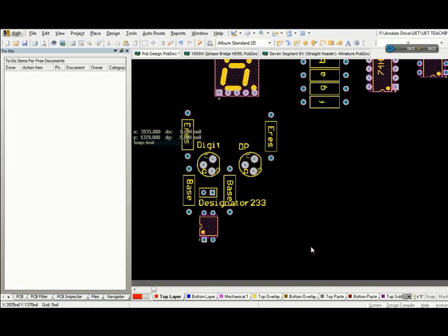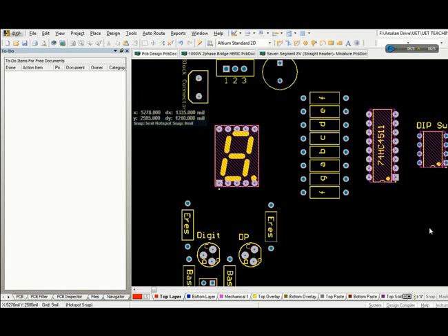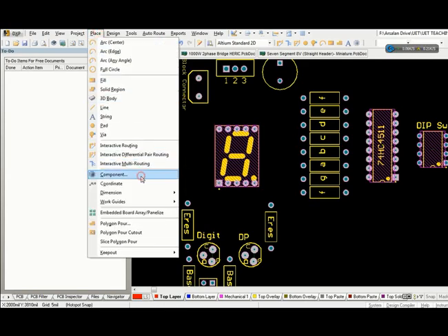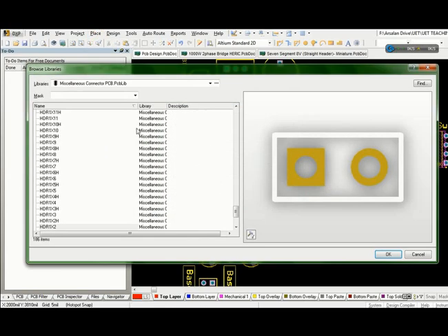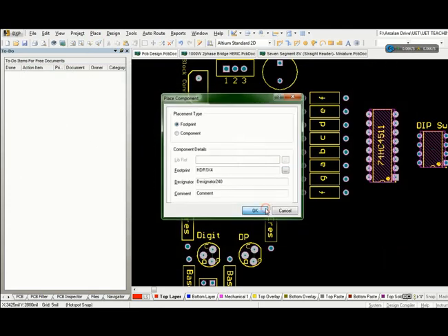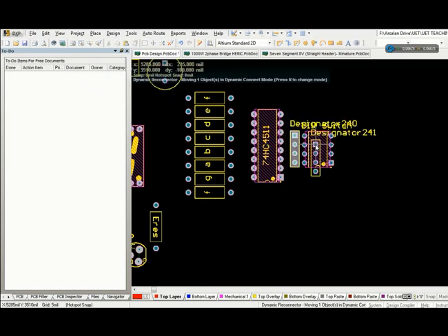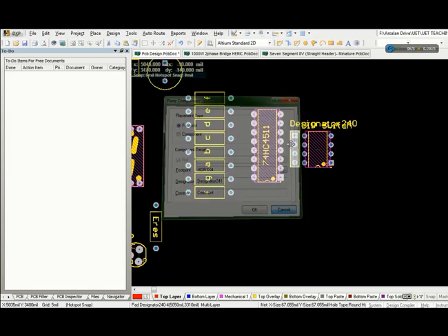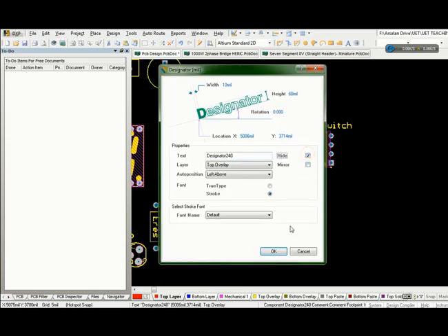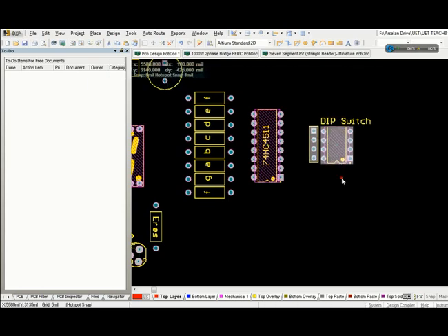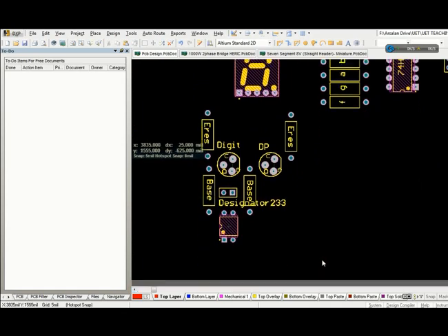I will hide the overall structure, because too much of the yellow color on the PCB creates difficulty in understanding the whole PCB. After some time, when you become an expert in all this, it will be easier. Here I require a 4-bit switch, so I am going to place that 4-bit switch over this side. Please remember the male header switch is selected on the other side. The dip switch is added so that it can give a 5-volt signal if the male header is not providing anything. So the male header is just coming in parallel over there.